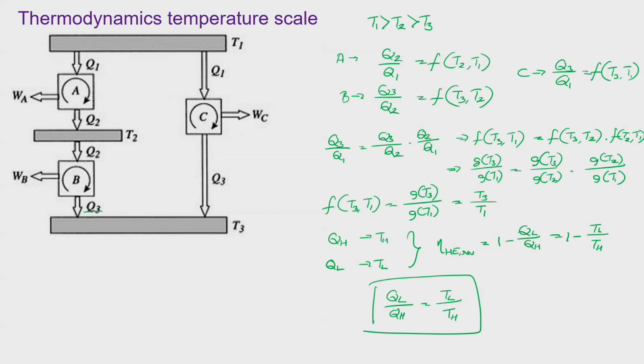Now, think about the Celsius and Fahrenheit scales. There we specified those 0 or 32 values based upon one physical phenomenon, which is the melting of ice under atmospheric condition. Now, if the pressure changes, the corresponding melting temperature will also change, and then we can't identify that new melting temperature as 0 because the condition has changed. That means the definitions or references in those scales are dependent upon the properties of some fluid, which is not the case here.